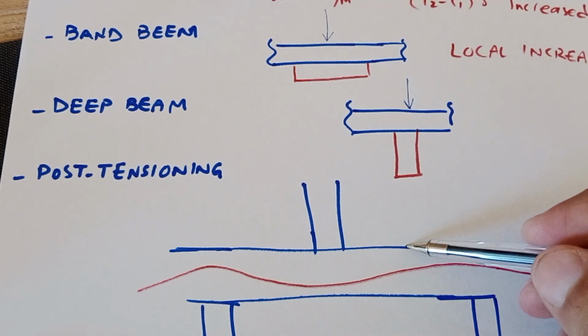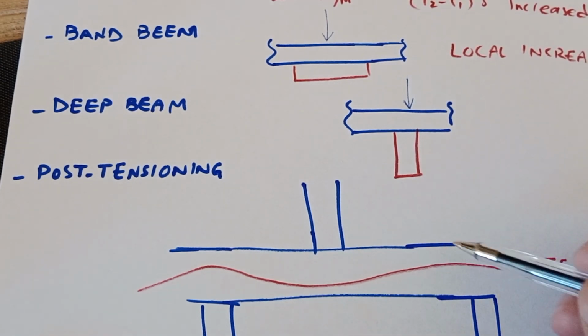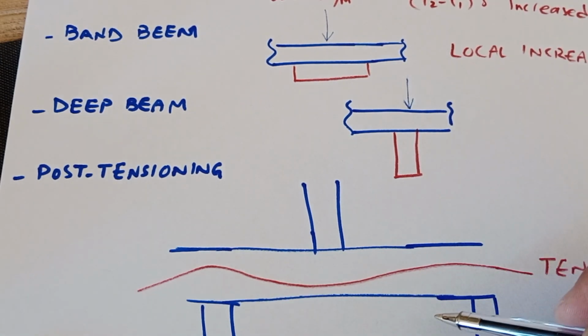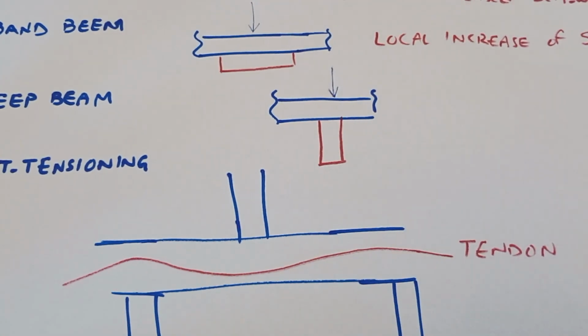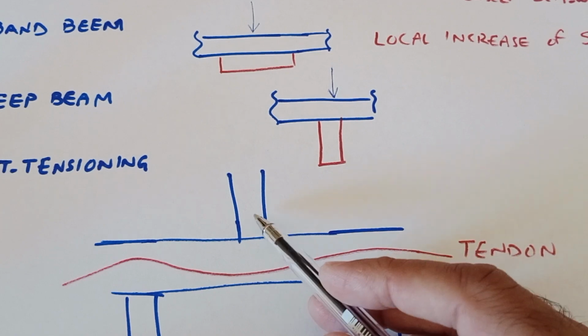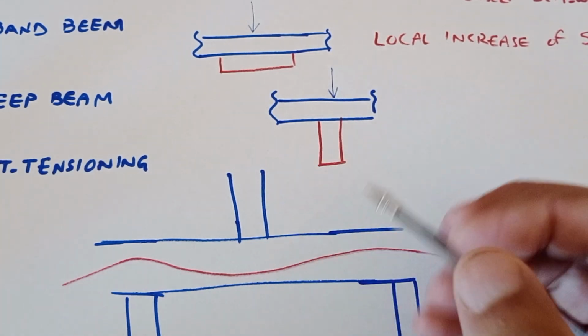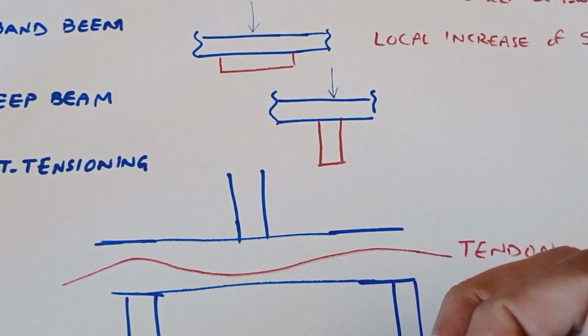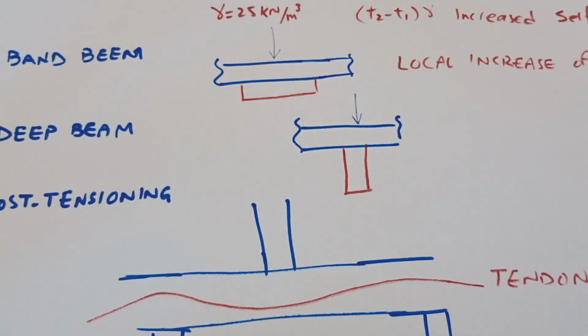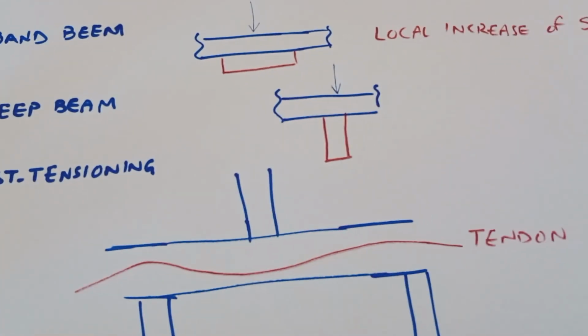If you are not able to change the thickness of the slab, let's say you are dealing with about a 200, 300 mil slab thickness and you can't change it for any reason, an option can be adding tendons to lift up the slab under the point load, under the increased load, and at the same time it can give you better stiffness and punching shear capacity. Remember, you can do this even in just one transfer floor, and you don't need to have it in all floors or identical floors.